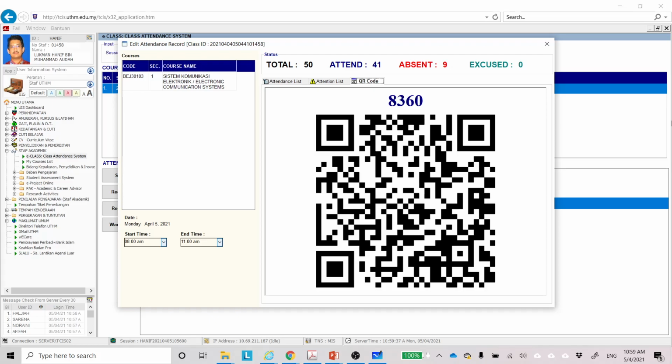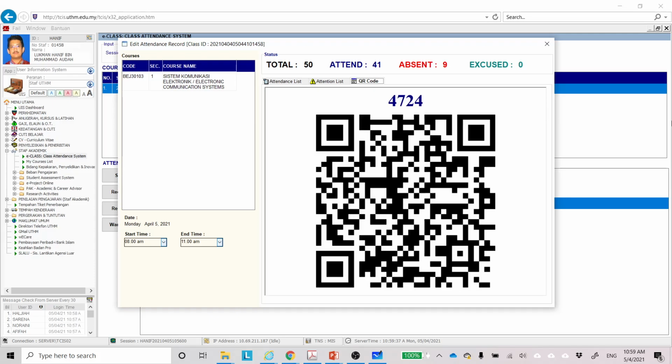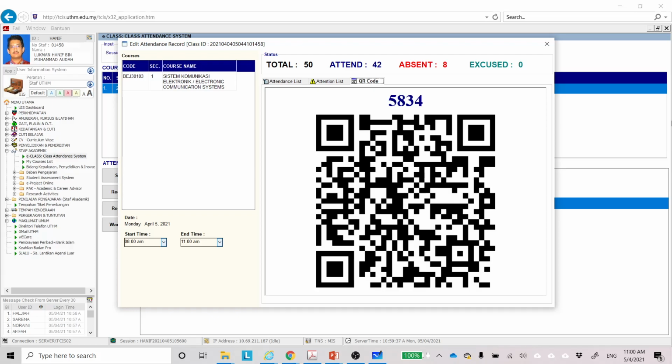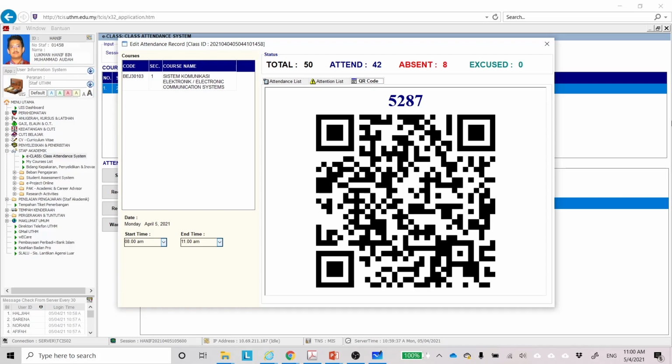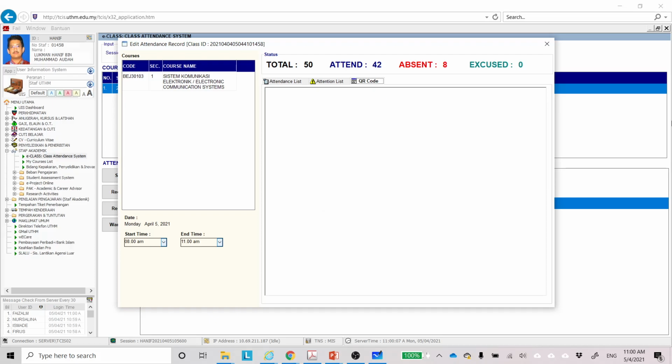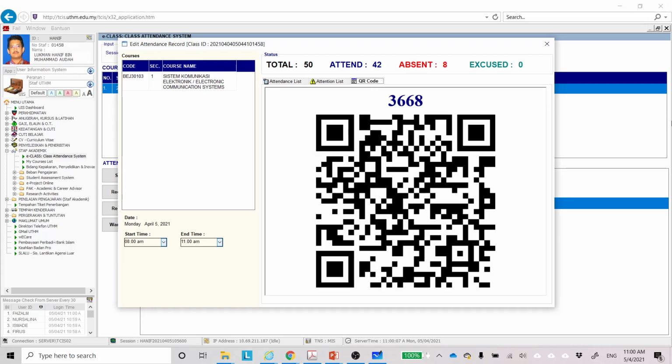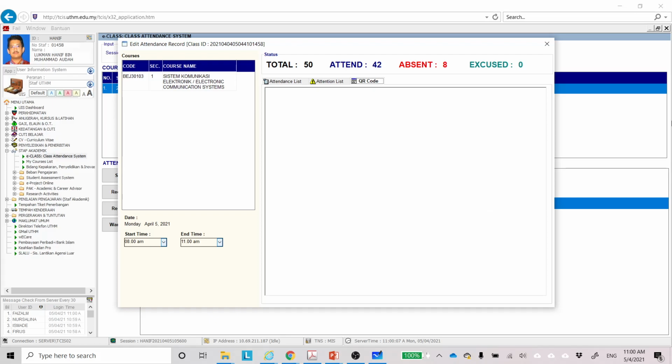So you need to put the value of the input frequency and input amplitude or power, and then the frequency of the carrier and the power or voltage of the carrier. Then, during the modulation process, what are the output values and what is the graph at the output. So you have the input graph, the input signal, the carrier, and then the output graphs and the output values.